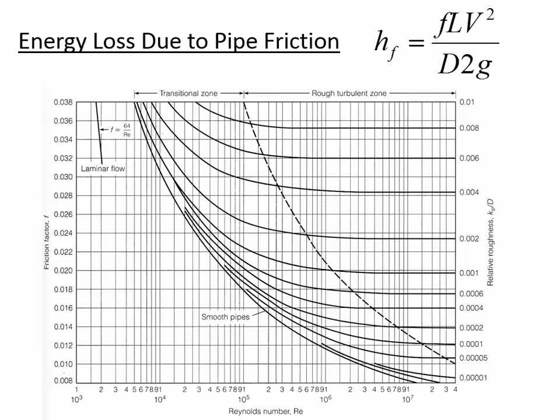So if a pipe is rough, it's going to induce a lot of turbulence. So think about the water that's flowing through a pipe that's like this, because the water is going past these boundaries, it's going to cause more turbulence than if the pipe itself was very smooth. If you have relatively small ridges, then that's going to cause less of a disturbance in the pipe.